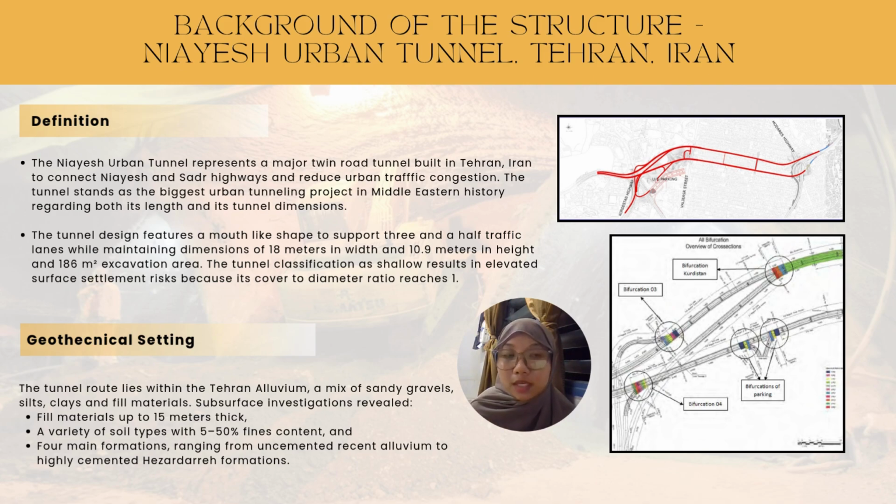Due to its shallow depth, the tunnel poses a high risk of surface settlement. The tunnel passes through Tehran alluvium, which includes sandy gravels, silts, clays, and fill material, all of which influenced the excavation and support system design.